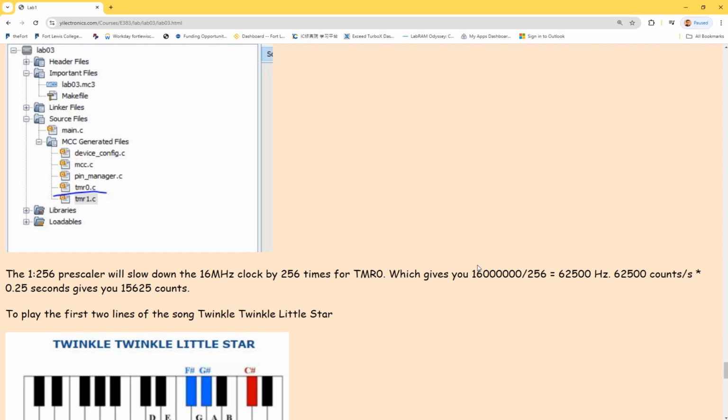So you need a pin to write to the speaker, and it's giving a command to the speaker by pressing a button. So what's happening is you press the button to start the music, and then one of the pins is writing different frequencies to the speaker. So you need the pins, one pin taking the input, and another pin outputting to the speaker. 2 pins, actually 3 pins, because we have two different music pieces. So upper pin, bottom pin, the 2 buttons on the board. You press the top one, play one music, press the bottom one, another one.